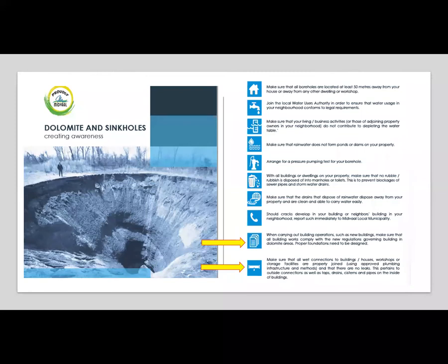As there's pressure being put on and the pump's trying to push the water to the top surface, it starts to leak in that pipe, and that leak then causes erosion. Obviously, no one knows and no one can see, but only through maybe a pressure test, you'll be able to determine, wait, there's a leak and we need to attend to it. Obviously, you don't want to have erosion happening around that pipe. It could be a very huge section that is eroded away, and you'd be sitting on some huge dangers there.